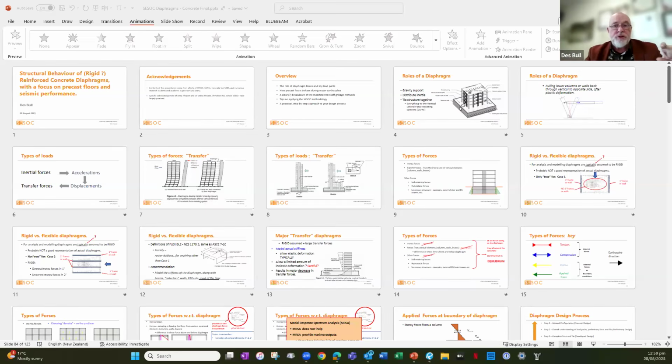Go and actually use those ACI or ASCE guidance for stiffnesses. That will give you a realistic distribution of forces through your floor plates and up into your vertical systems. And then you transfer those actions into the strut and tie grillage model that we're doing here. So yes, definitely model this using those ACI recommendations as a good place to start.